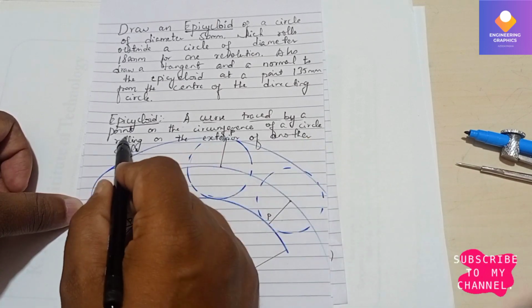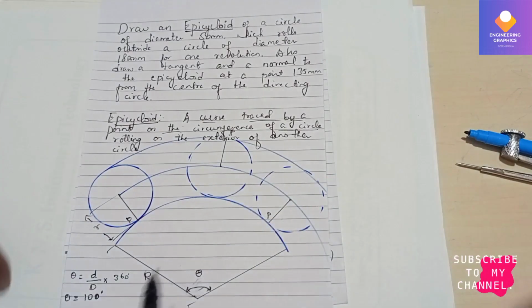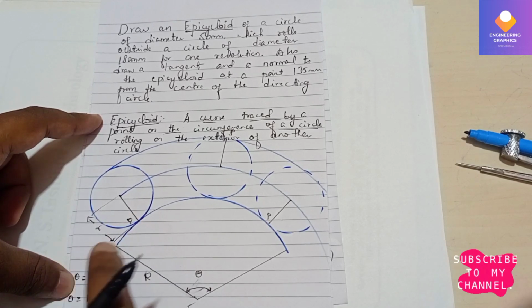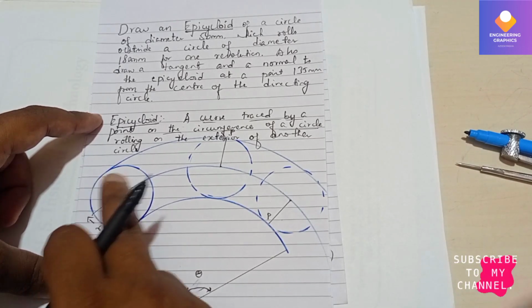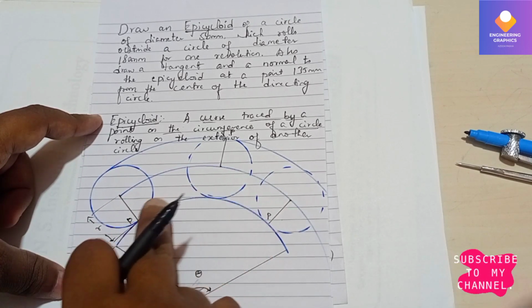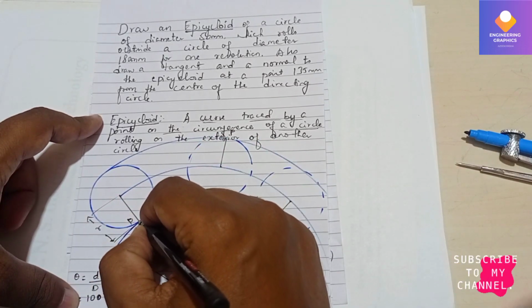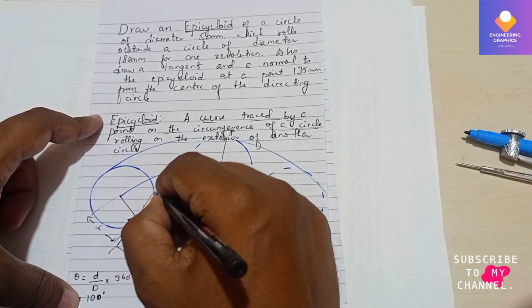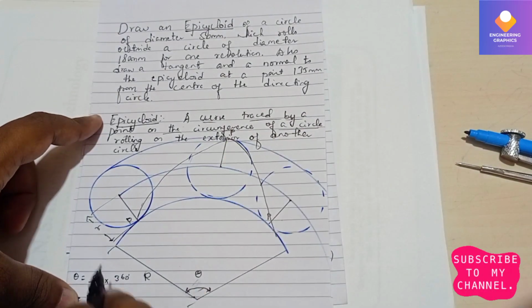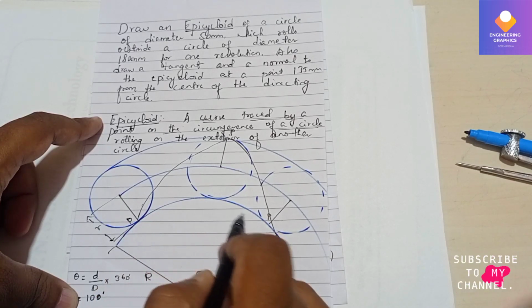It is a curve traced by a point on the circumference of a circle rolling on the exterior of another circle. That means here there will be two circles. One will be the bigger circle, one will be the smaller circle. If I consider a point on the circumference of this smaller circle, as it rolls over the exterior of this another circle, it is tracing a curve here. Say, just for an example, if I join from here to here, then again from here to here, like this, that is the curve traced by a point on the circumference of this circle as it rolls over this another circle.